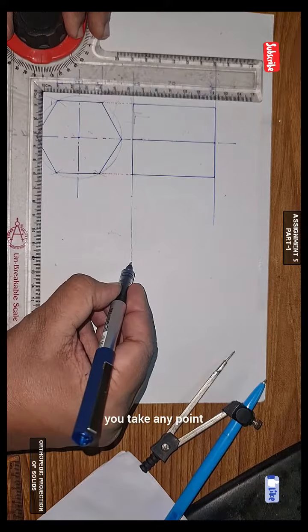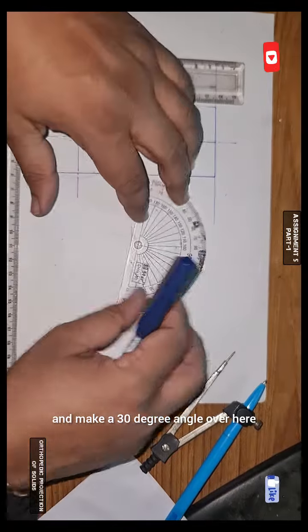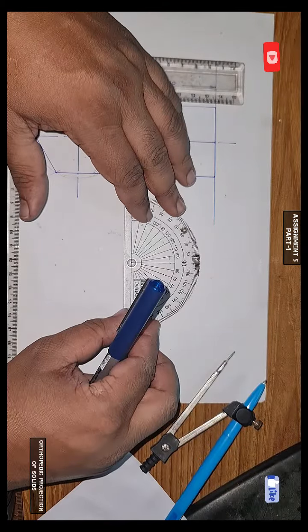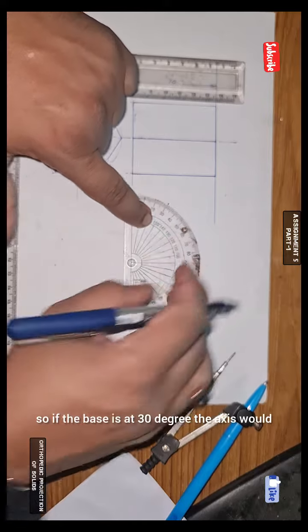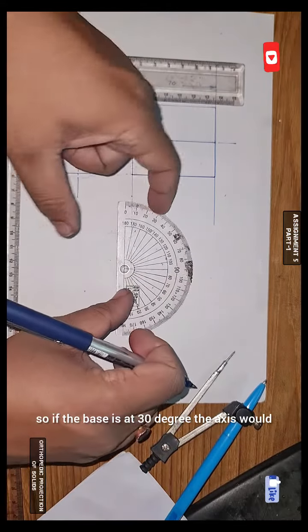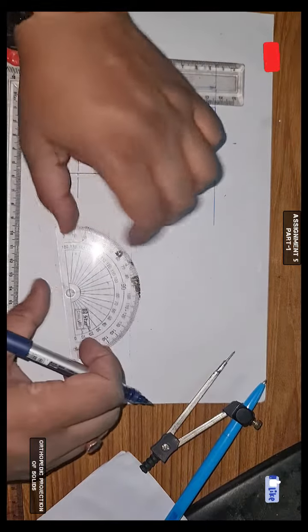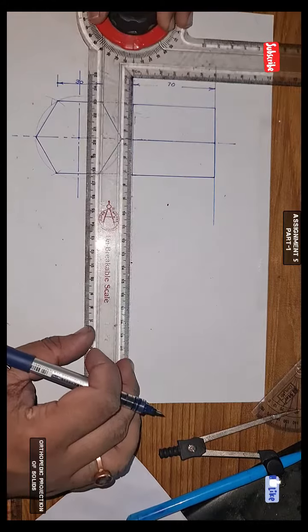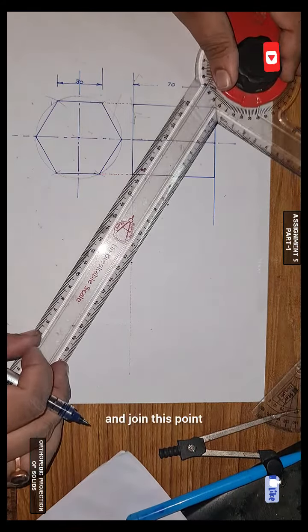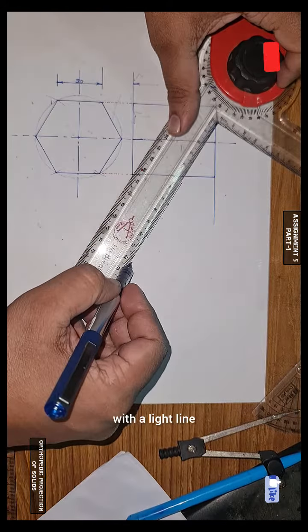So you take any point and make a 30 degree angle over here like this. So if the base is at 30 degrees, the axis would automatically become 60 degrees. So you take your drafter and join this point with a light line.